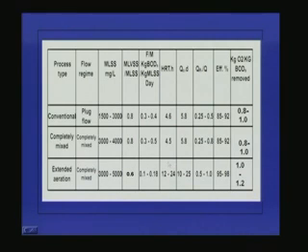Now, we will discuss the food to microorganism ratio. In an extended aeration system, the food to microorganism ratio usually we keep very low. The value varies between 0.1 to 0.18. Mostly the microorganisms are kept under starvation. And now we talk about the hydraulic retention time. It varies from 12 to 24 hours because the entire microorganisms have to get oxidized. That is why such a long hydraulic retention time.